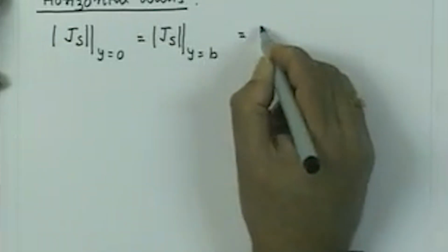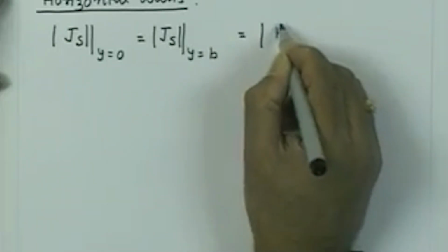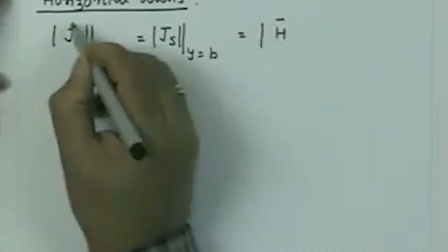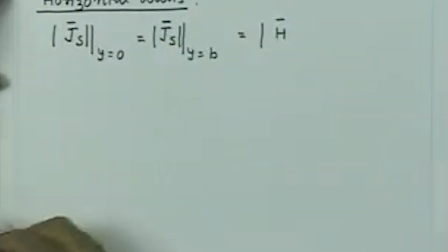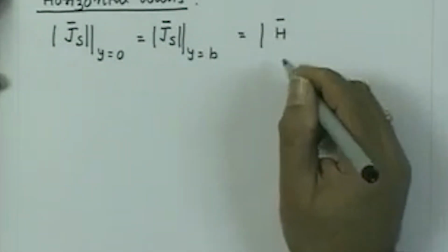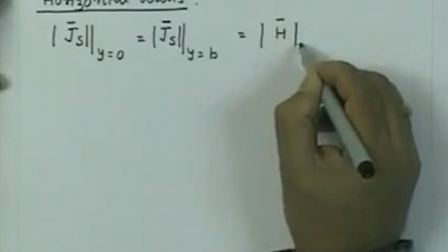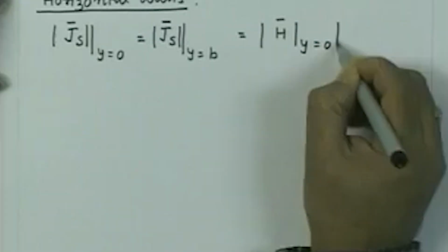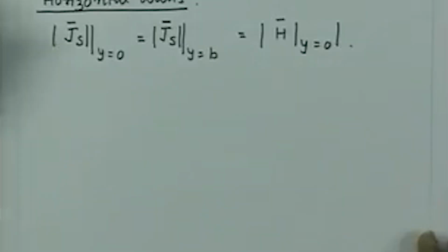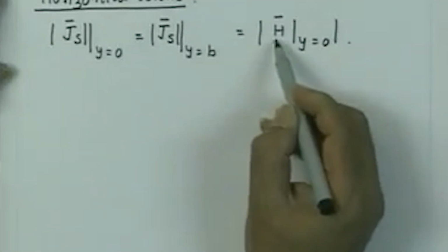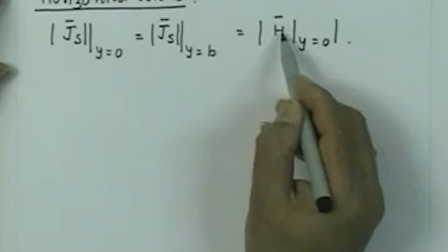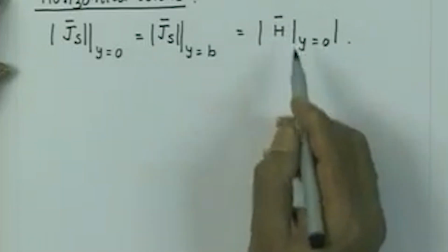That is what will be needed in our power loss calculation. So, that will be equal to mod of the magnetic field. Js is the vector quantity now, because it has two components x and z at y equal to 0. So, first you find out the total component, which is the magnitude of the two components Hx and Hz.